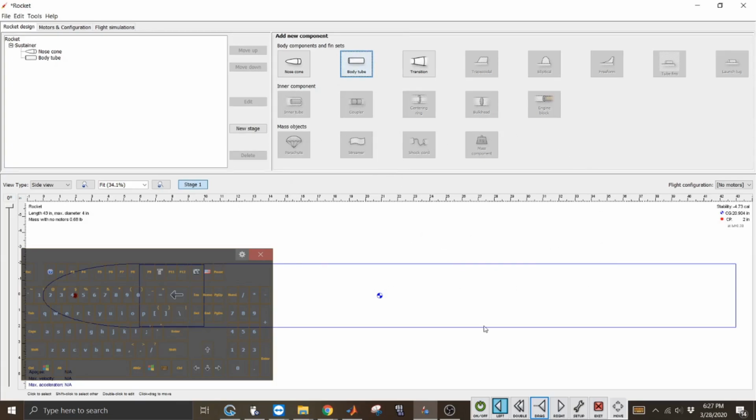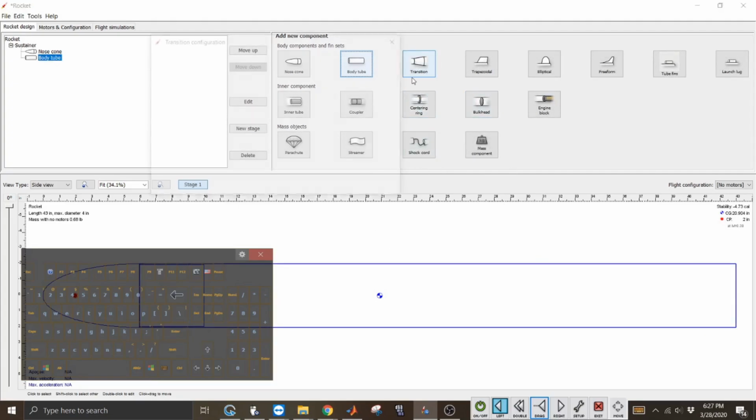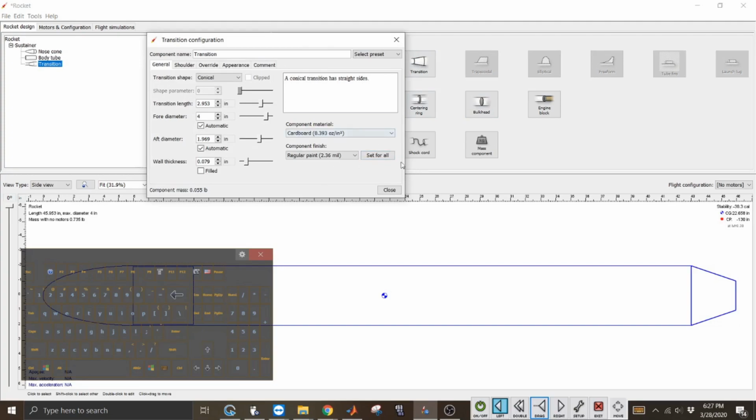Now, we are gonna be using removable fins, and what I did when I did the NASA student launch competition is we included a removable fin can system, which essentially had slots in the airframe for the fins to slide into, and then we had a boat tail. This is what we came up with the name, obviously. We had a boat tail that served as the cap, or it holds the fins in place.